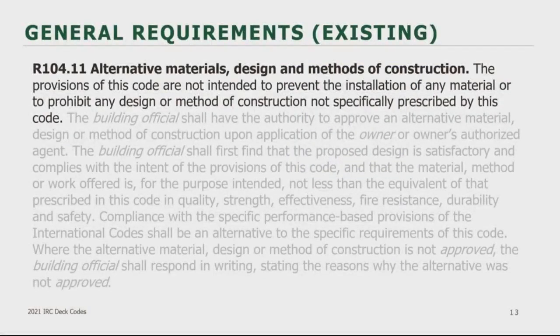So there's 1,000 paths to code compliance. Many residential decks use some sort of alternative methods and materials. Let's break this section down a little bit. I should note that this applies to any section of the IRC and not just decks. The first sentence says that just because a design, a method of construction, or a material is not prescribed in the IRC, that doesn't mean it's prohibited. On a deck, new products are being designed and approved every day.